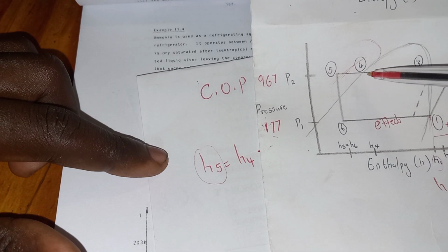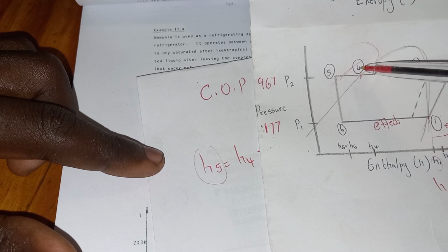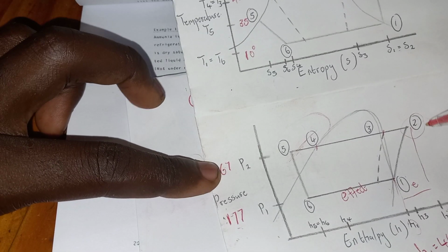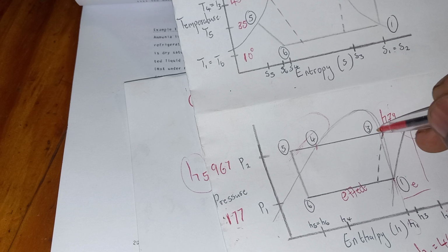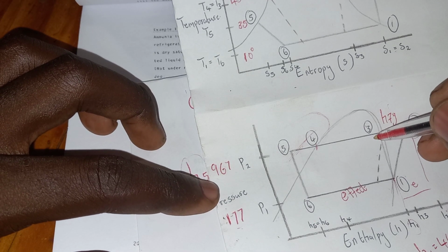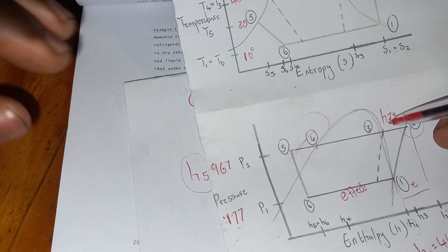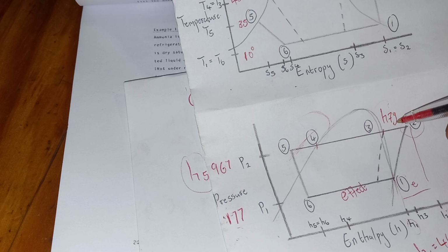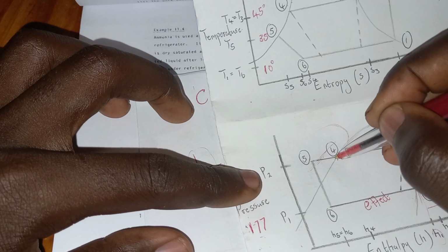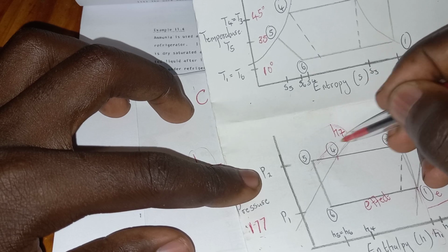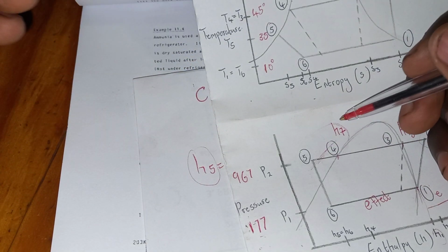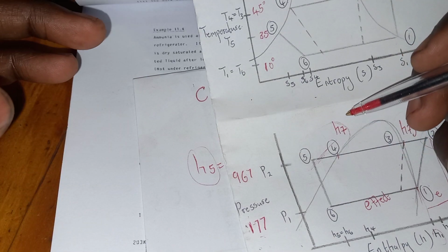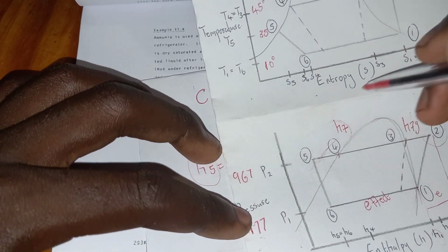So when it changes into water, the heat energy here, this one is your HF, but from here it was HFG, because it's what? It's the heat energy released by the evaporator, or the evaporation heat energy, which is called the enthalpy of evaporation. But here now, because this one is changing into water, therefore we're going to read HF, because it's the liquid enthalpy, the heat energy that comes with water. So when it changes into heat energy, then we can go to our table again.